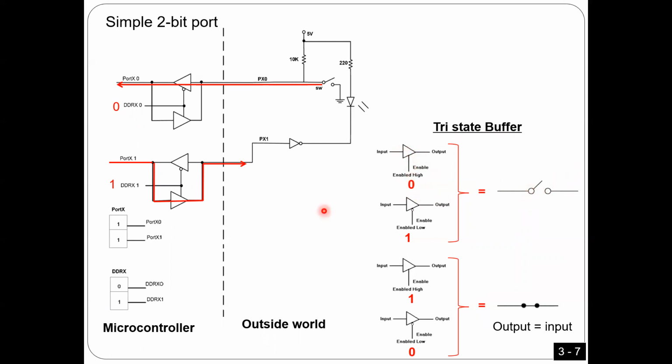Here, because this one has a bubble, if you put 1, it means it's open, right? Same thing here. If you put 1, that means you can make it a short circuit. If there is a bubble and you put 0, you connect the switch. It's an electronic switch.